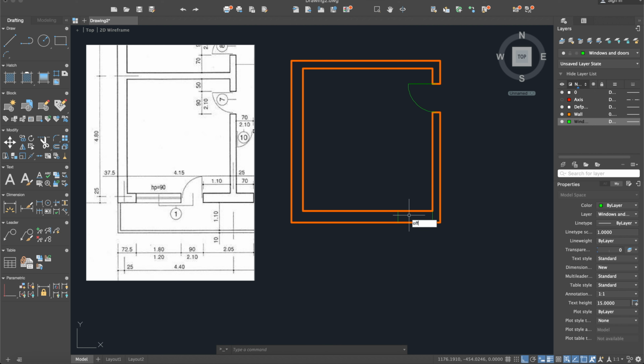And our door is also 90, as can be seen here, so offset 90. Wonderful. Okay, now I must convert these two into walls. Use the trim command again, select those two lines and all the lines, press enter. Again, trim, select, enter, and you can trim it.